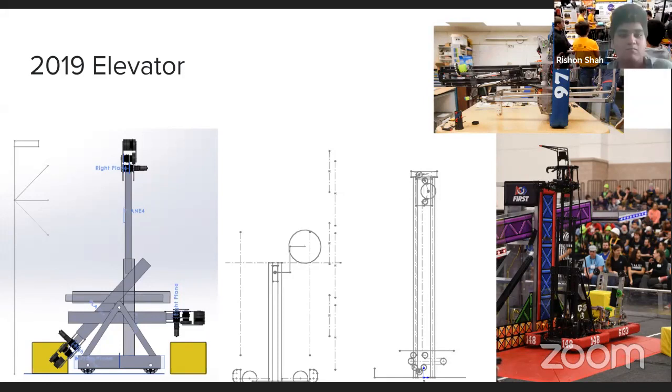No, I think you got it. A lot of our prototyping, we CAD a lot of our prototypes as well, depending on the prototype, obviously. For things like shooters, we would CAD prototypes of those, cut them out of wood, and then assemble them, and make places to mount motors, mounting encoders and things like that. So you can do a lot by CADing wood and using a CNC machine to cut it.